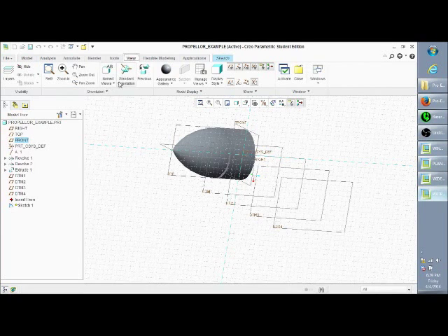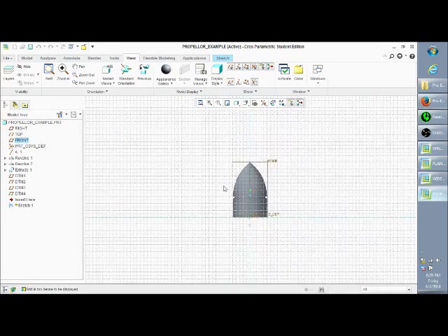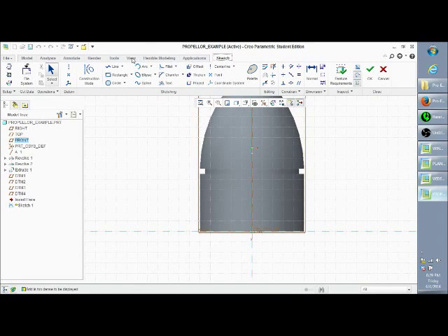What you want to do is go in and view it from the side. So I believe it is the view and then top, and you get a side view. For this sketch plane, we want to select the reference. We want to add the top line going across it as a reference, because this first shape will be a circle, and that will start from the center of the cone, and it will come out and then go from the circle to the airfoil shape.